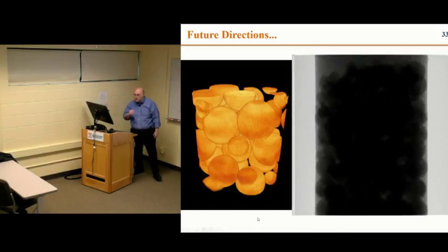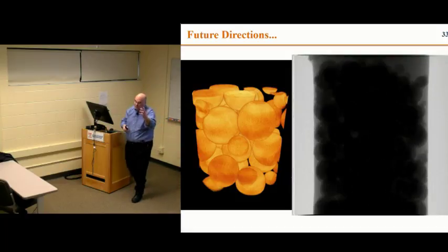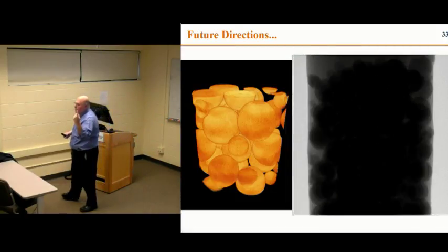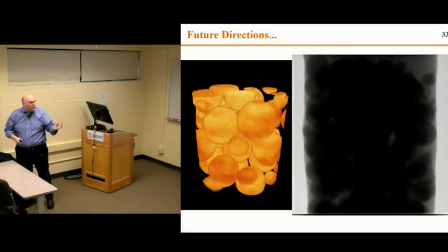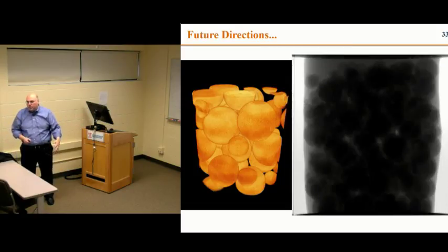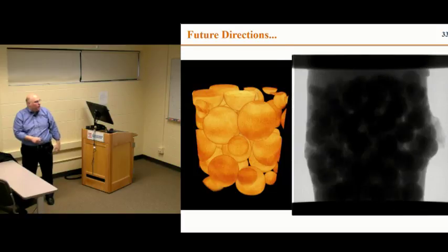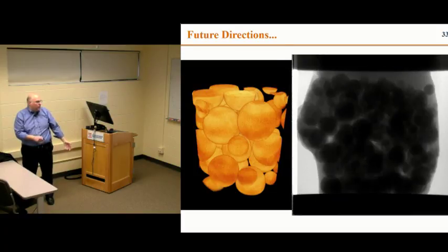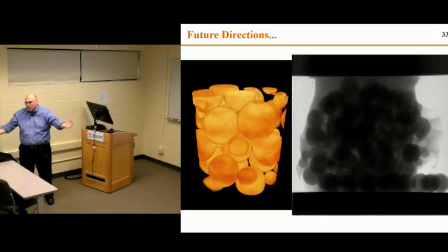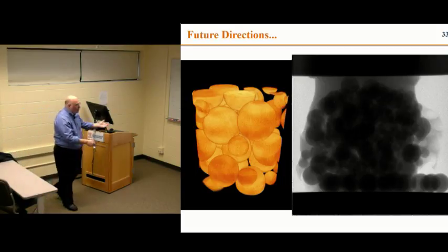So this is a series of radiographs. This is the raw data, our 2D radial scans as the thing is going around. And these are concatenated throughout the entire loading period. So this is several hours of measurements, right, while the loading is progressing on a very high volume fraction composite. And you kind of already see it's starting to bulge out, and then at the end it fails and they all come out.